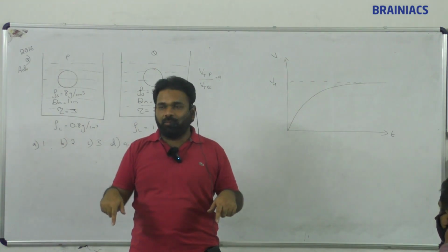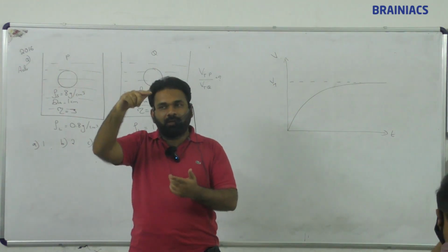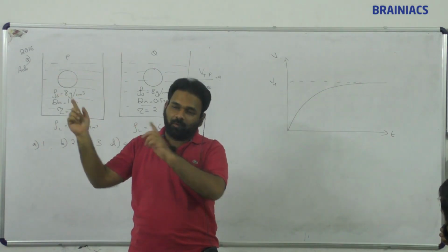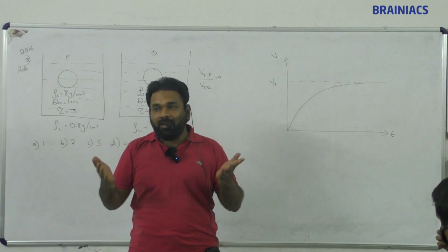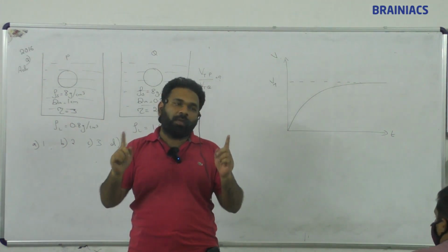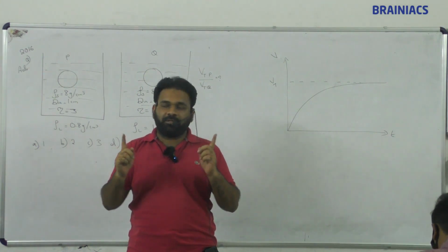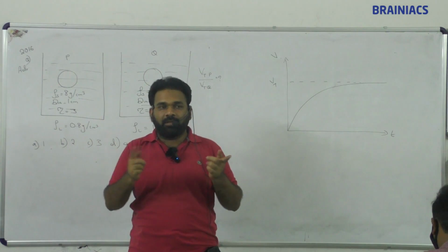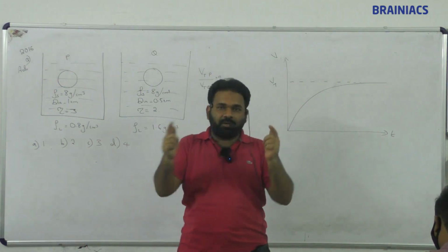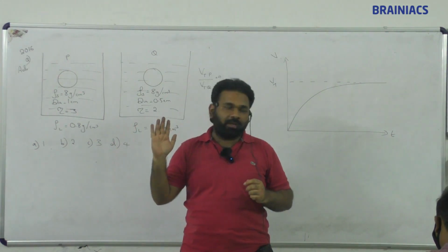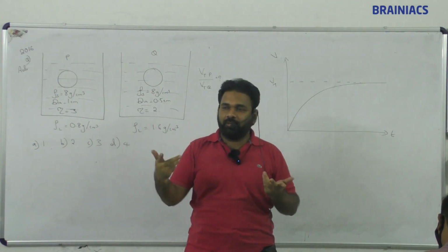If it is moving down, the pressure difference is H rho g minus a. If it is accelerating rightwards or leftwards, the pressure difference is going to be L rho a. What is the angle of inclination? Tan theta is equal to H divided by L. The relation between H divided by L is equal to what? a by g. Okay, then what else have we studied after that?